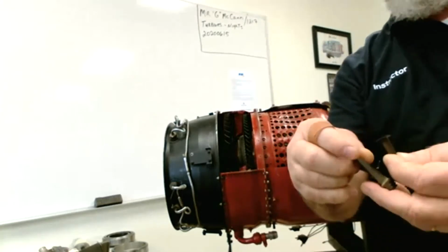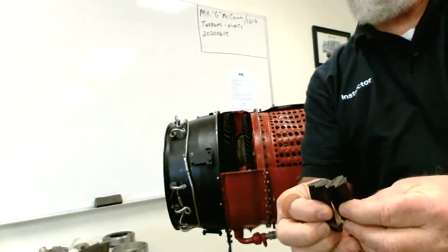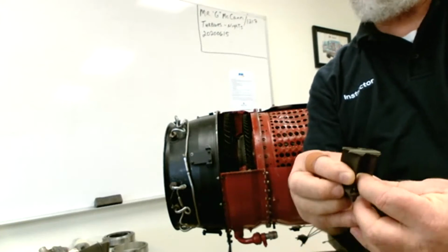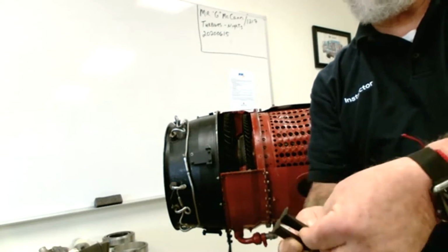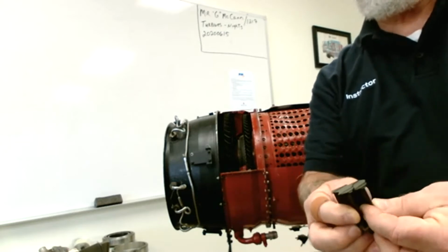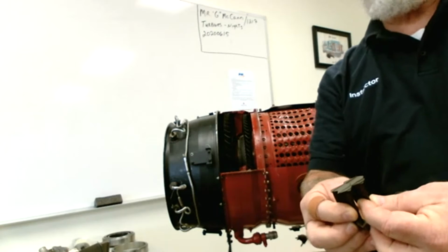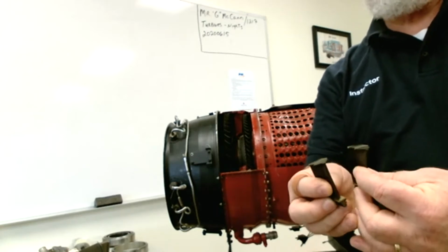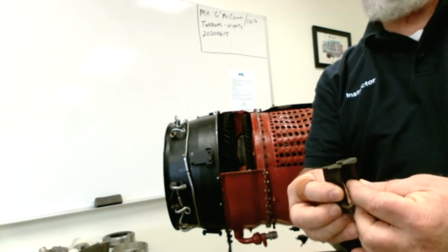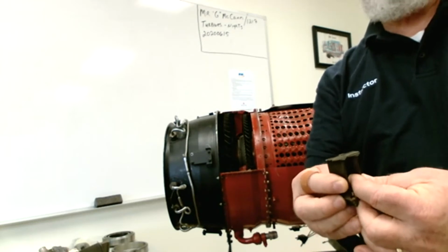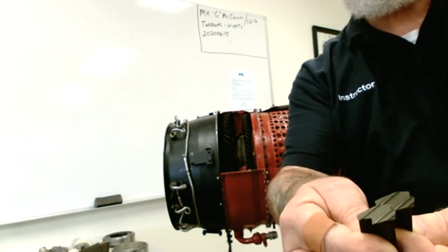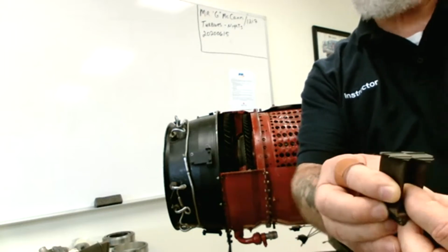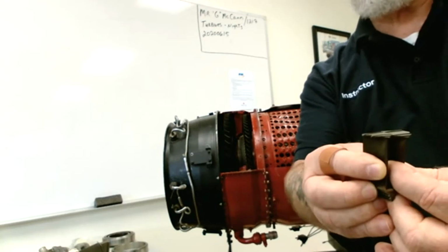Some turbines utilize a blade that has a shroud on the outer part. So if you were to put those all together to make a complete disc, you would see that they're shrouded, right? The primary advantage to a shrouded blade is that it does prevent vibration. These do move a little bit, and with the shrouding, it helps to prevent excessive vibration. Also, there's an aerodynamic quality: these knife edges on the tips ride inside of a channel, and they make the blade a bit more efficient.